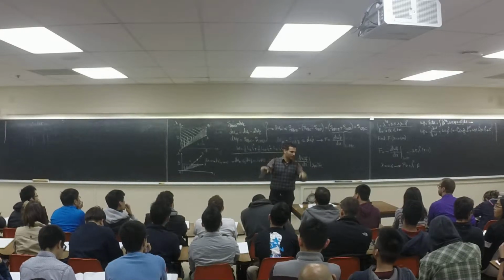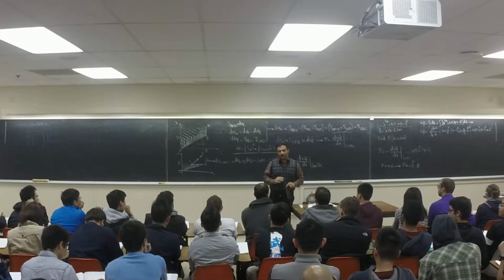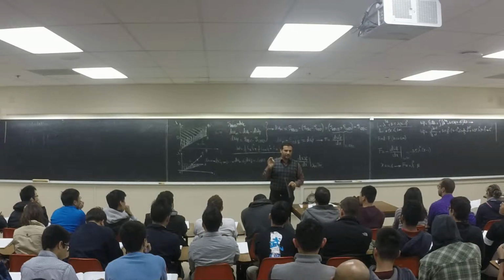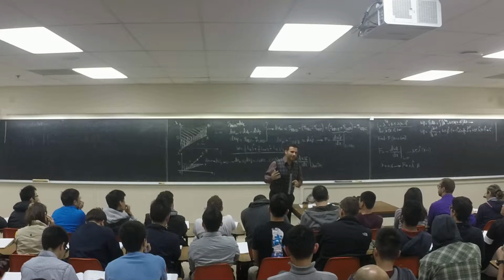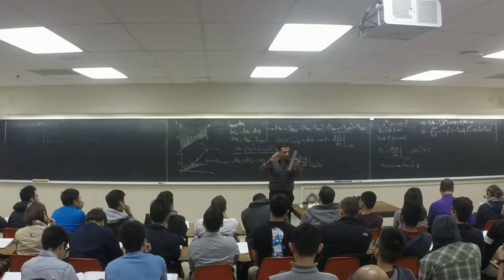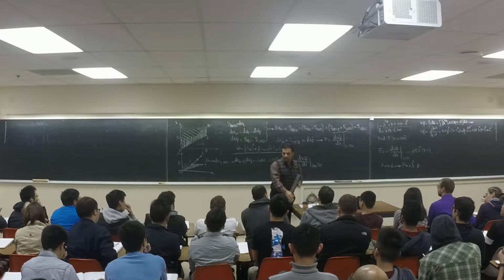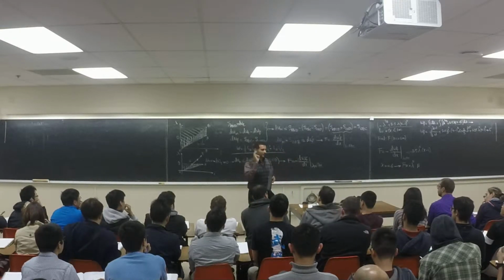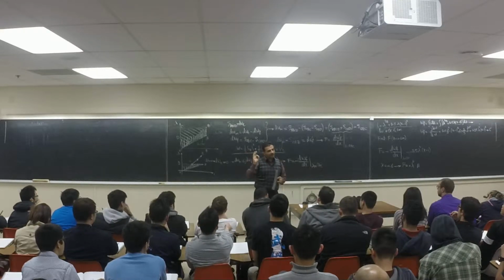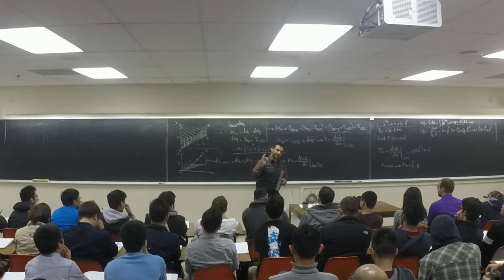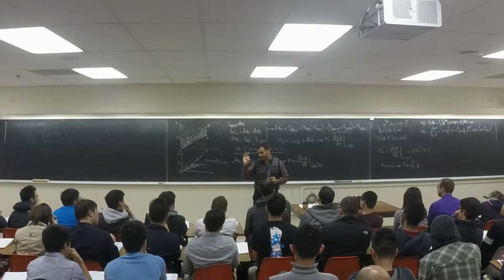Usually they are cylindrical, and there's a moving part inside. I'm not sure how familiar you are with finite element. Finite element breaks down the whole system. For example, the more the better, 10 million elements. A small motor, for example, about 3 times the size of this coffee cup, gets 10 million elements. They become very, very small pieces, right? So when they become very small pieces, we can consider them linear. Inside that little piece, we can consider it linear.